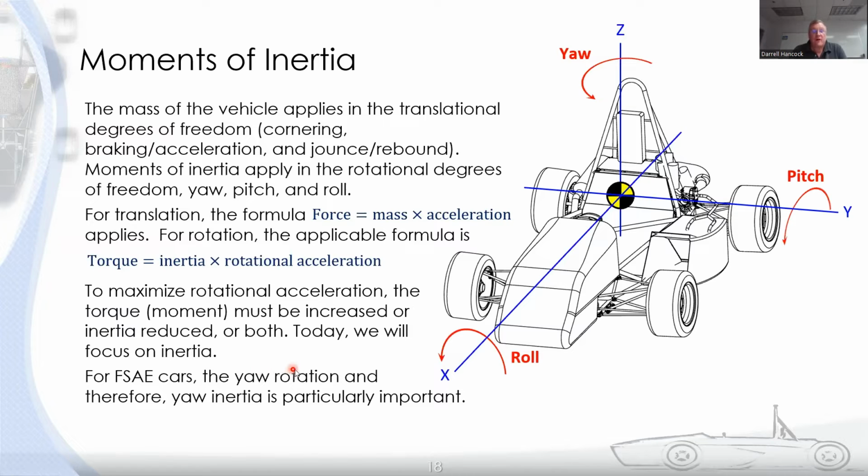So for Formula SAE cars and in the Formula SAE competition, the yaw rotation is the primary aspect of interest. The bounce and pitch moments of inertia are significant, but not nearly as important as yaw.